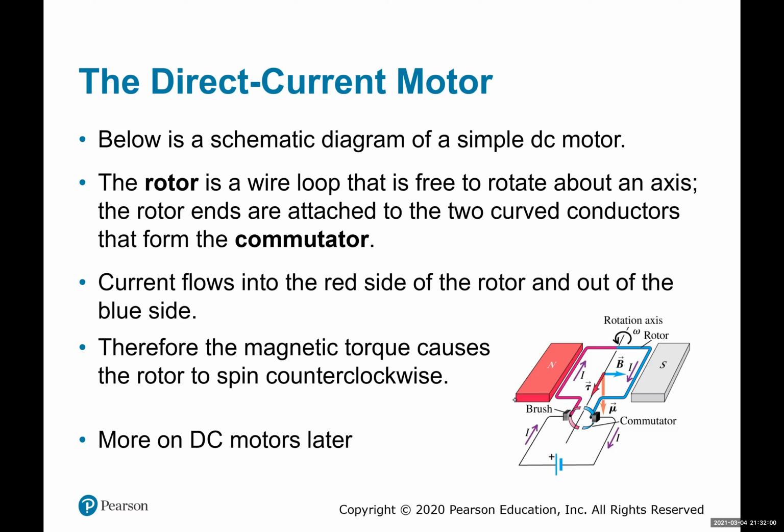If we change the direction of the current, now once we're here, we can keep going because we've just passed through, we're at the maximum potential energy of the reversed polarity situation. So now we keep going and we can maintain a constant rotation that way. So that's what the brushes and commutator are for, so that we can keep a constant omega. Otherwise, it would just reverse direction back and forth.